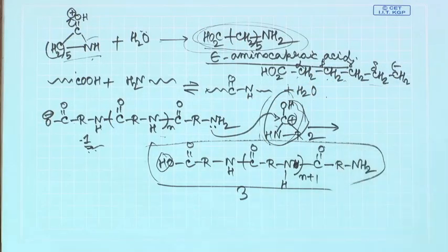So, we will stop here today, and we are not yet done with polyamides, because we have talked about aliphatic polyamides until now, and we have talked about self amidation process, we have talked about ring opening polymerization process, and both we have talked about together, because self amidation is one part of the whole polymerization process when you are doing a ring opening polymerization. And we told that especially for caprolactam, if we are trying to prepare nylon 6 by ring opening caprolactam, then basically self amidation accounts for only few percent of the polymer product, mostly it goes through ring opening polymerization.